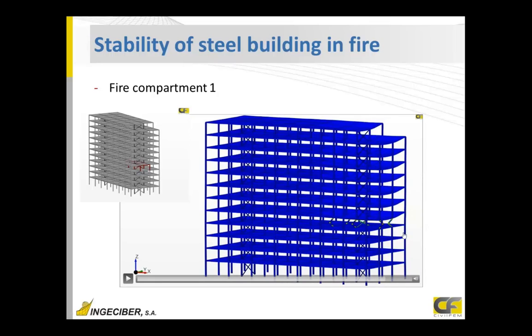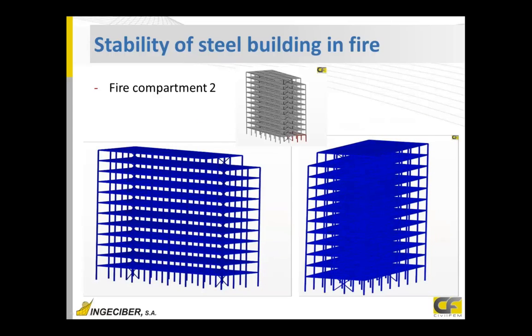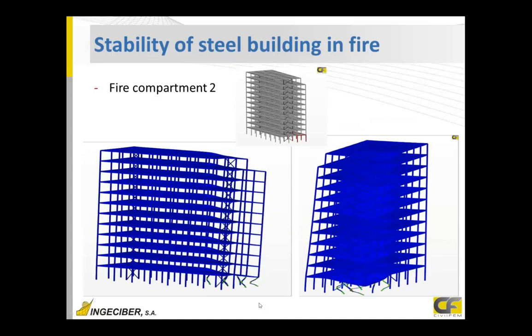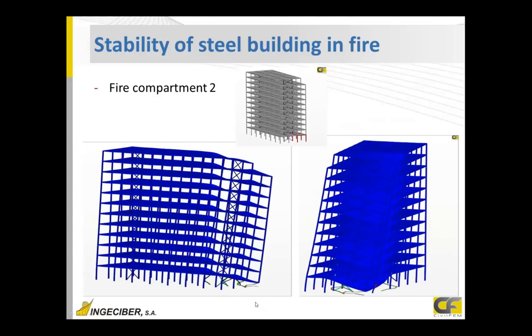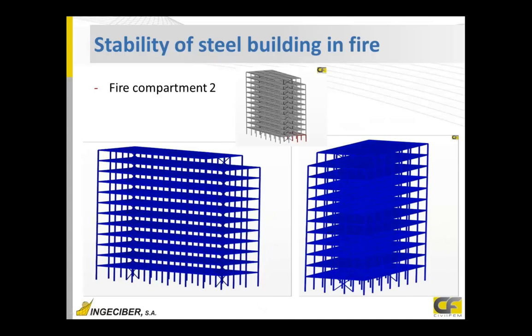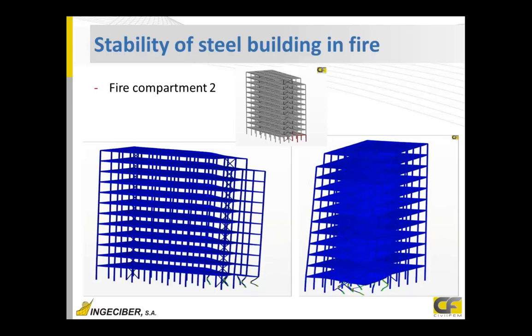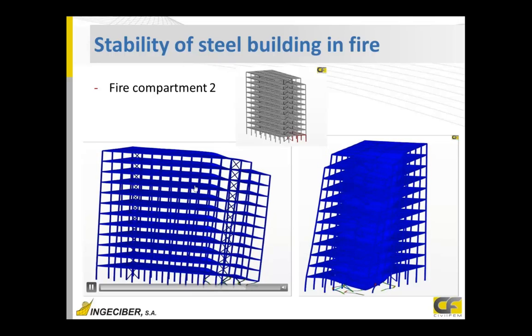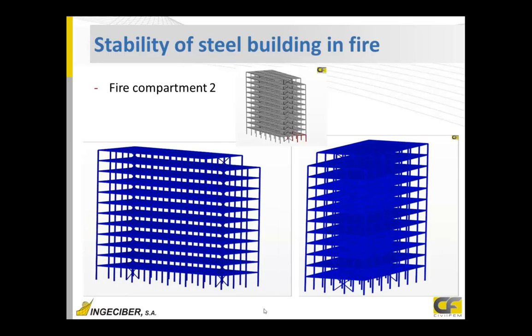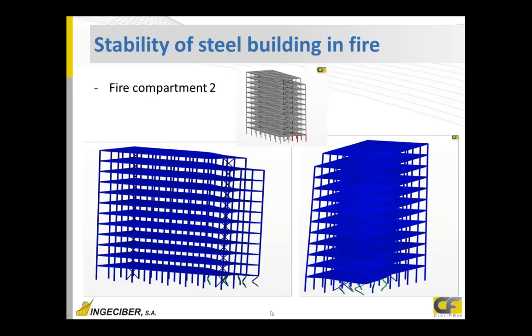The elasticity modulus is reduced and yielding is happening in this part, but collapse doesn't happen. For the next example, fire is in this part. So we can see that after a minute it is yielding and collapse of the structure happens. So this could be useful for knowing the time we need for evacuating the building, or if we have to reinforce different parts with better fire protection.